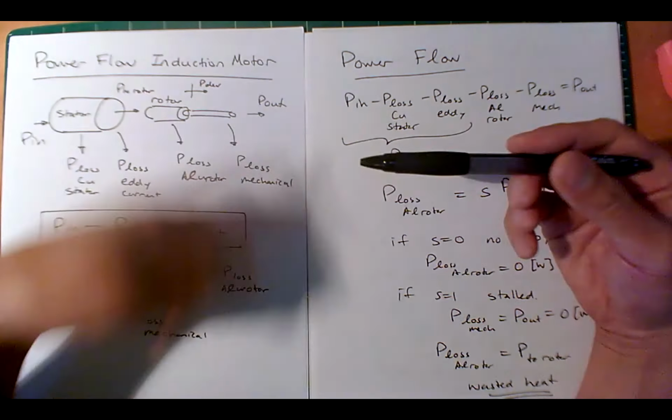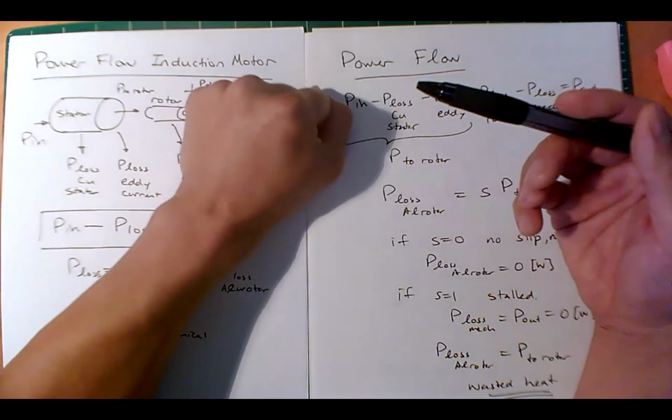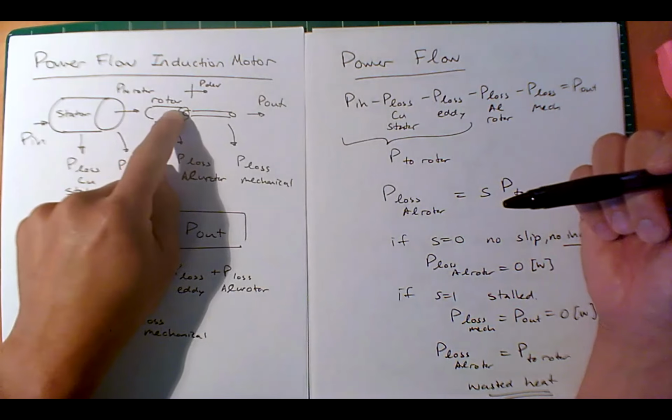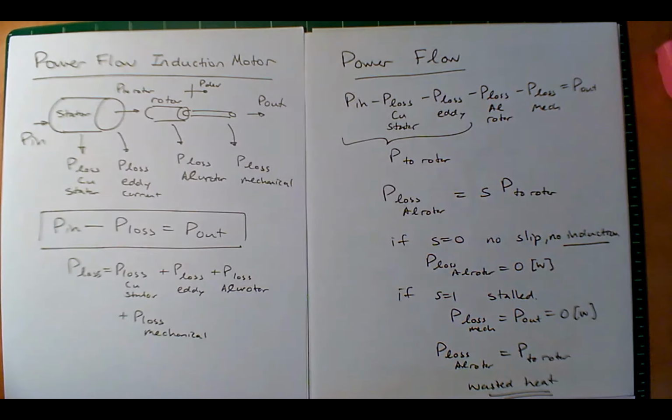So the synchronous speed is going round and round, and you're holding the shaft here and not letting it move, right? And this rotor is just getting hot. That's all that's happening, okay?